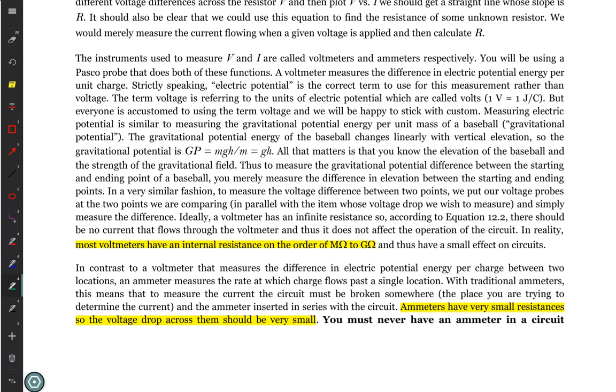These two connectors here are your voltmeter. And notice it says red plus. If you put it on something, it will measure a positive voltage if the red side is a higher voltage than the black side. So you need to pay attention to where you connect these to get the right sign for your voltage. Then here, where you have to put wires in, is the ammeter.